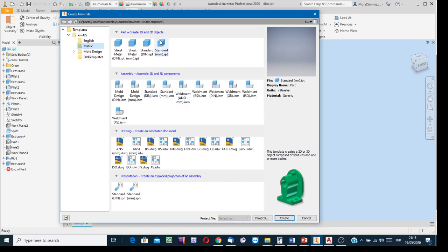Okay, and create the model of the component while inputting the constraints as dimensional constraint or coordinates of characteristic points. Sure, Inventor will record the written numbers in millimeter. You know this quite well. But say that it is a civil engineering product, the model of the walls of a house, for instance. I recommend in Inventor, do not change the default configuration. Create the model of the object using millimeter.